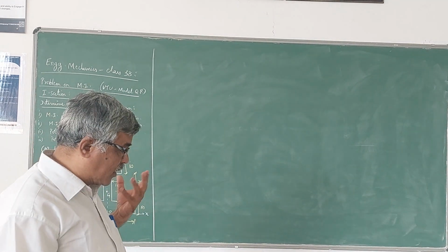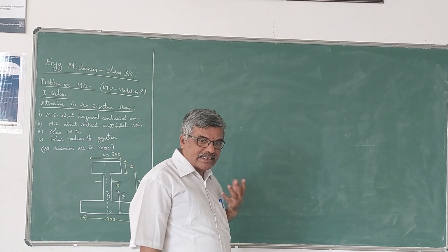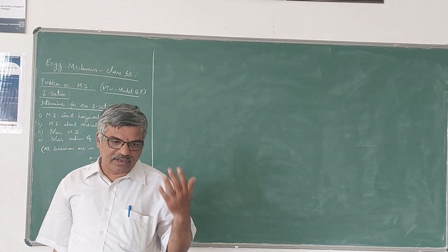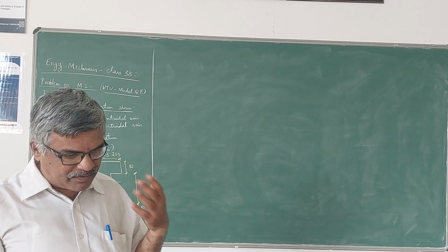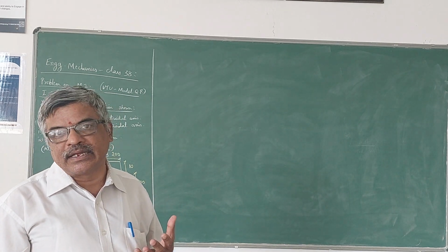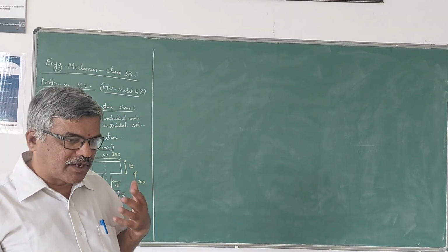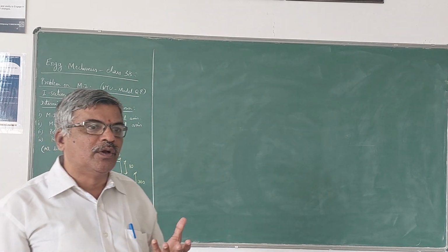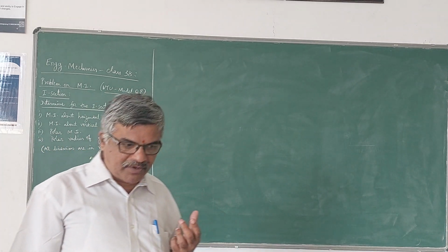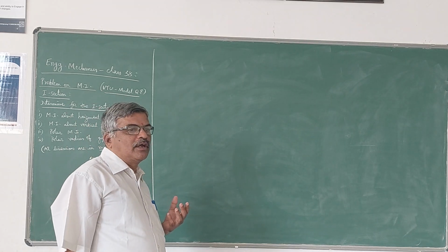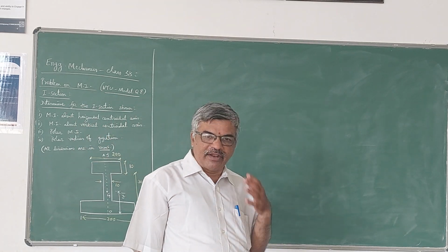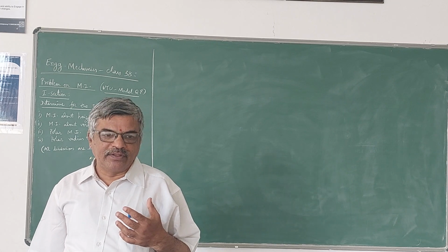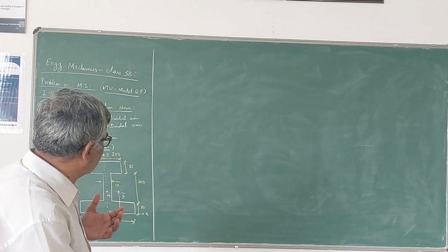As I already told, as the value of moment of inertia increases, the strength of the member increases, and it can take more load. Flexural strength will increase because flexural strength is directly proportional to Young's modulus and moment of inertia. So therefore, computation of moment of inertia is very important in the analysis and design of structures.